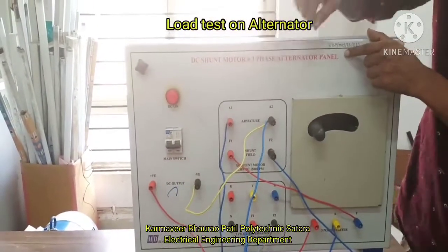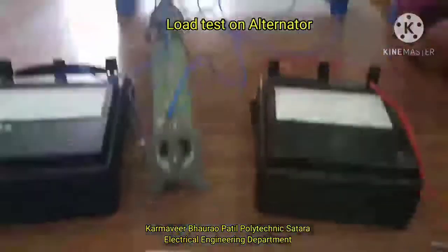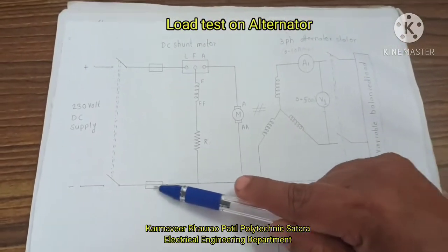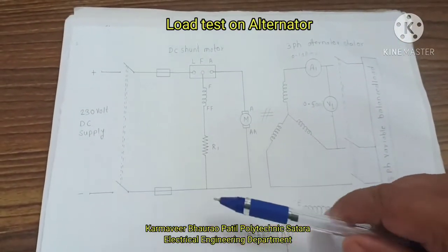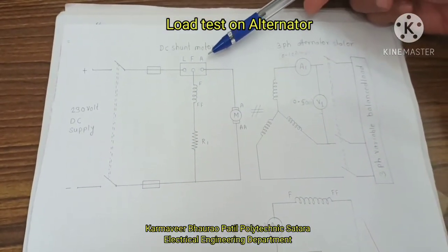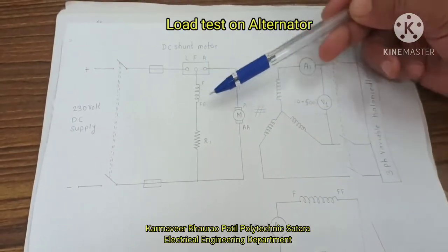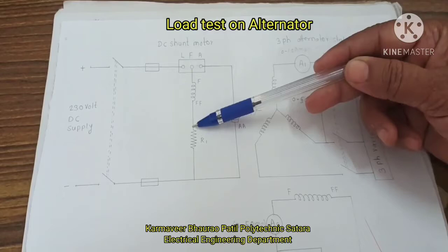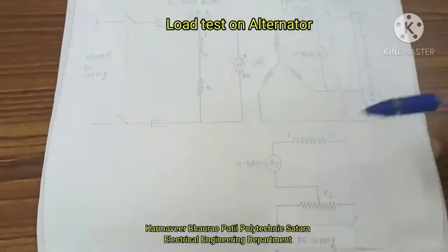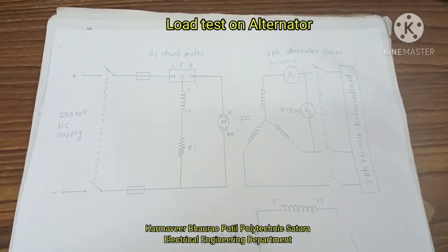That means the variable terminal of the rheostat and A2 are to be connected to the negative terminal. So starting from the starter, we come to the armature A terminal, field F terminal. Then F2 goes to the rheostat fixed terminal, and the rheostat variable terminal and A2 together go to the negative side. That was the connection for the DC shunt motor.